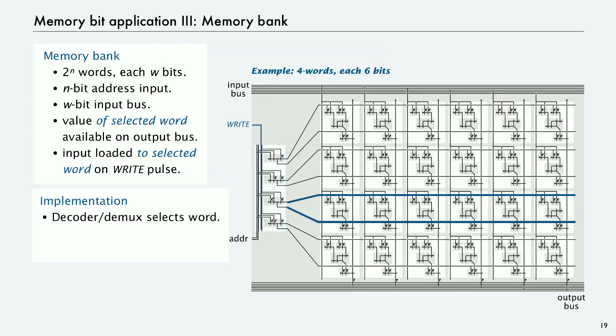Remember, we take the address bits, and then there's a value that comes in, that's the write enable. So there's exactly one pair of lines that becomes high. That's what the decoder demux does for us. And all the rest of those lines are 0.